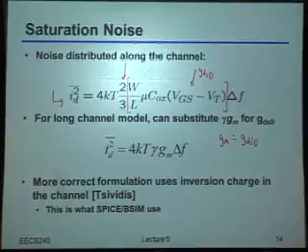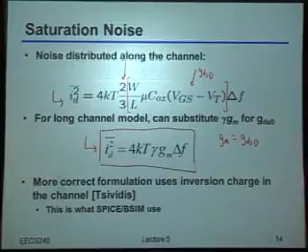Okay? So in terms of the conductance, we have the same conductance as we had back in the triode region. Just that because it's shaped by this weird channel distribution, there's that gamma factor in front. Then indeed, I can now just say that my overall drain current density is 4 kT gamma GM. Okay? Where again, that gamma GM is just replacing the GDS naught. By the way, this is the expression we'll be using probably the most throughout the entire rest of the semester. So it's worth remembering.